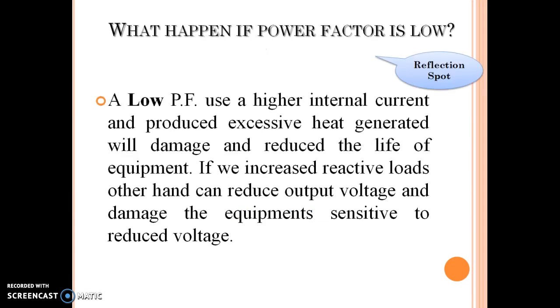Next slide is what happens if power factor is low. A low power factor causes a high internal current and produces excessive heat, which will reduce the life of equipment. Increasing reactive load, on the other hand, can reduce output voltage and damage the equipment.